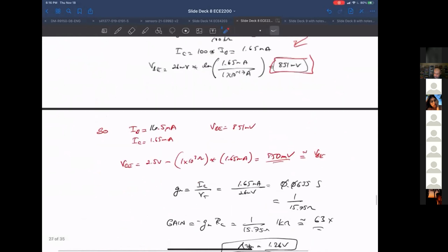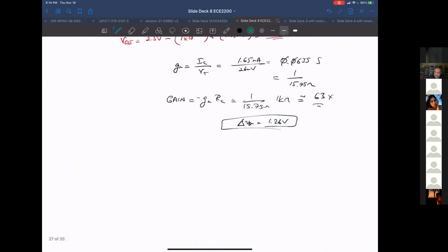But Brandon, you might have missed this at the beginning, I was looking through a data sheet for a typical bipolar transistor, and even if you buy 100 of the same model, some of them would have a beta of 50, and some would have a beta of 150. They would have a big range of beta values. So this beta for a real product is not constant, unfortunately.